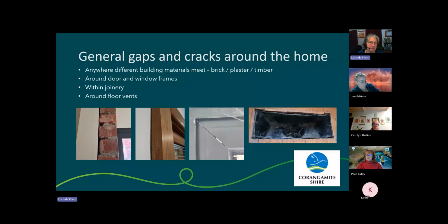Then there's all sorts of other gaps and cracks. So we're still with the filler rod and the caulking gun. I seem to recall this was a house that was quite new, and this had been built on, but just not finished off at all.